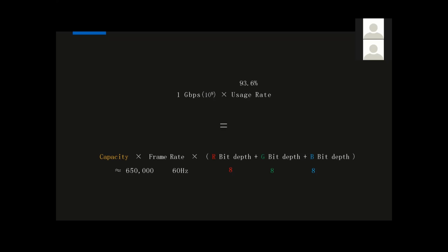And in other words, for example, in some urgent situation, you're working on site and one of your ports is just a little bit over the loading capacity, and you don't have another controller to split some panels to. In that case, by observing this formula, we can drop the frame rate from 60 to 50, then the loading capacity will be increased. So that can all be calculated by this formula.